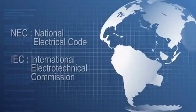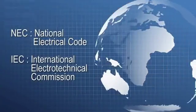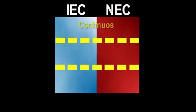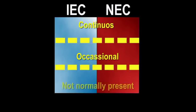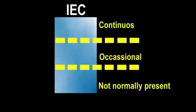The two predominant methods used for classification of hazardous environments are the NEC and IEC standards. IEC and NEC standards both classify the level of risk into three main categories: continuous, occasional, and not normally present. All three categories provide the likelihood of an explosive atmospheric condition within the general environments. Within the IEC standard, the general risk categories are then classified as zones. This reflects the physical material that could provide a potential fire or explosion.